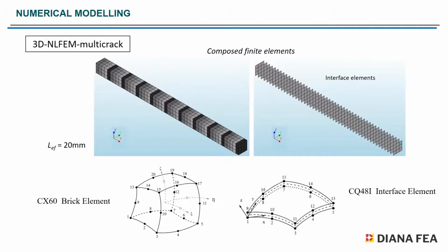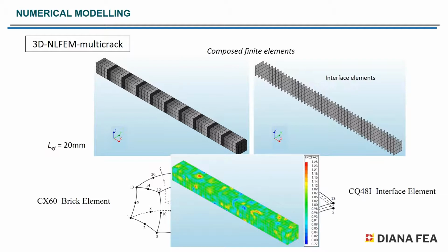And the 3D model is much more complex. The tensile elements here are modeled with 3D quadratic isoparametric solid brick elements, in this case with 20 millimeters. And between them, every 20 millimeters along the length, we have included quadratic plane 3D interface elements in order to simulate the micro cracking effect. Moreover, in order to have a better representation of the reality in the experimental test, as we know that the properties of the concrete are not always constant, a random field that multiplies the values of the UHPFRC tensile behavior has been added to better model this scatter, and the factors used for the random field have been adjusted based on the variability of the results obtained in the characterization process.